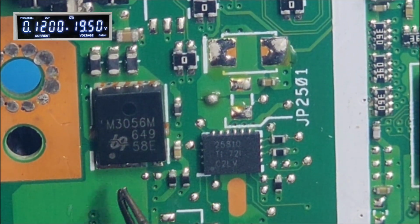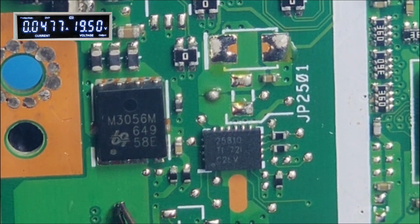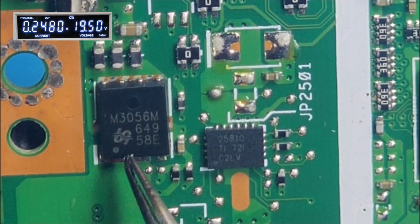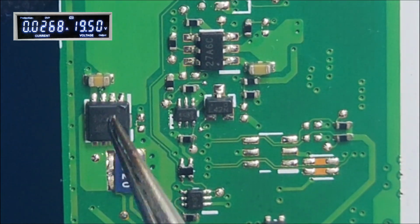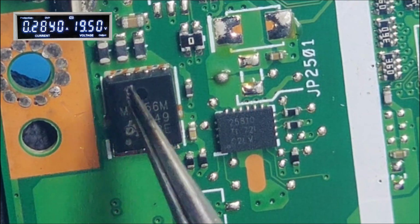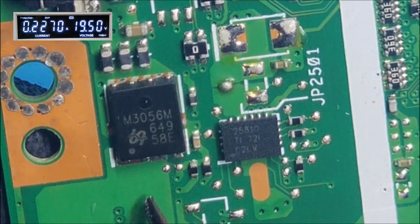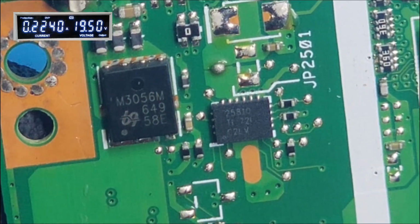So this is source and this is drain. An N-channel MOSFET always conducts from source to drain. So shorting the second MOSFET will not help us here, because the diode is in reverse blocking for the adapter voltage. So we need to short this one from here to here, so then we will get the voltage into the motherboard.